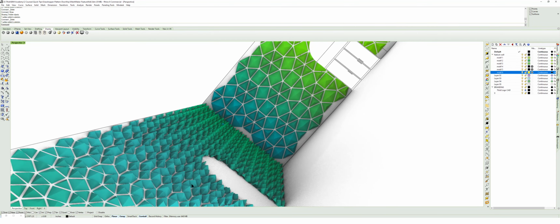Now, some of the prerequisites you're going to need in order to get going with this. A couple things. You're going to need M+ as a plugin. You're also going to need, for a couple things, pufferfish, paneling tools. Paneling tools will be how we get the grid length at the beginning, and then to bake out at the end for our components. And feel free to use whatever bake software you want. I'm going to be using Elefront to do that at the end.